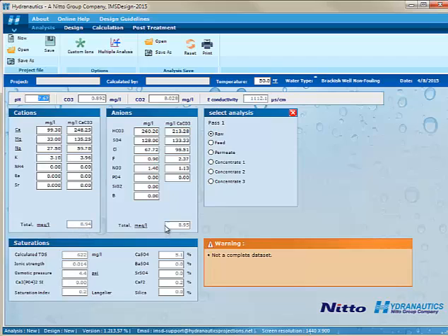You'll notice that your milliequivalent should now be balanced, but your calculated TDS might be different than what you have reported from your water supply that we looked at in the homework assignment. That's okay. I mean, we're trying to balance this. I think the data set that we were provided from the South Dakota DENR was incomplete, and there could be errors with the measurements or analysis that's there. So once you get this entered, everything's good.